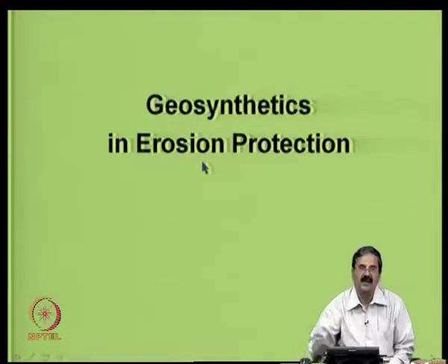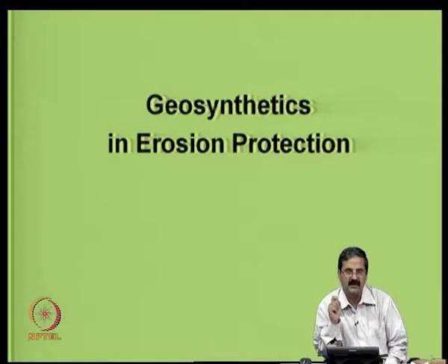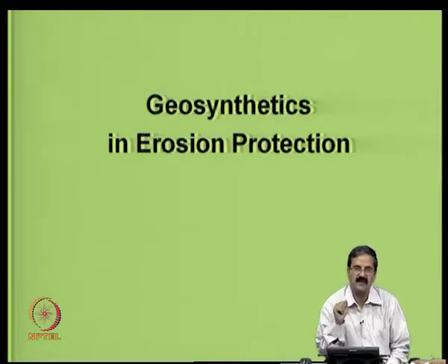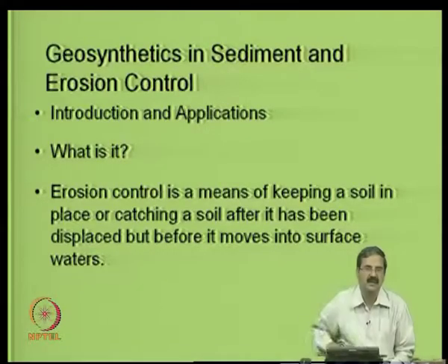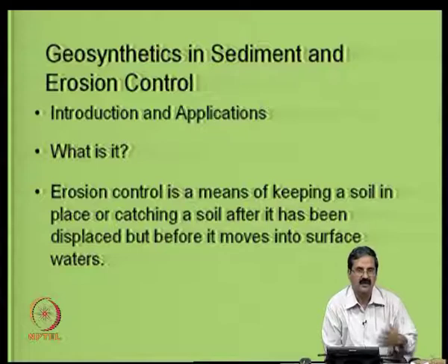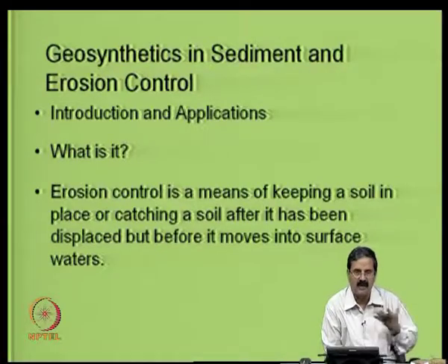The other thing that I would like to highlight to you is a very important application of the geosynthetics materials. Actually, it goes close to some of these two functions, namely filtration and drainage. The erosion control is something that is very important. And how do we use geosynthetics in this? Because erosion is one significant thing in soils, all rivers are getting eroded, all materials are, hill slopes are getting eroded, and if you want to prevent this erosion, only geosynthetics is one alternative.